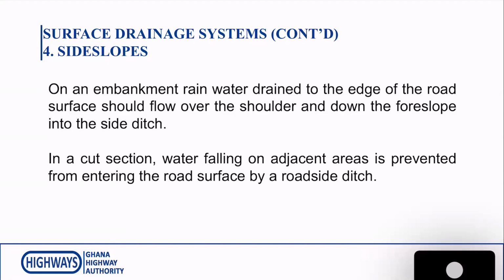Sometimes when the backflow on the embankment is high, one can place a transverse ditch along the side slope to trap the water and convey it to a convenient point to avoid erosion of the embankment.